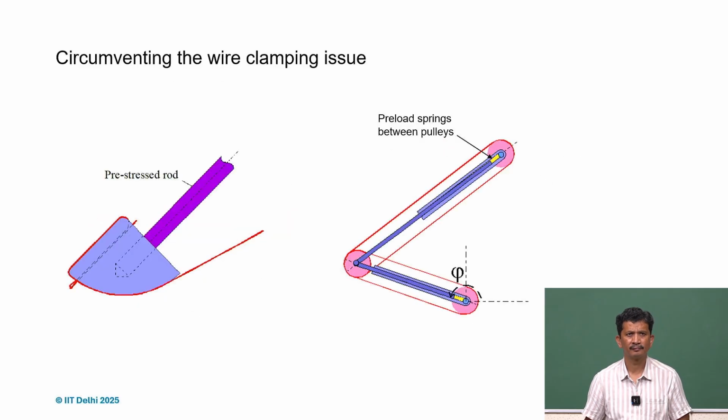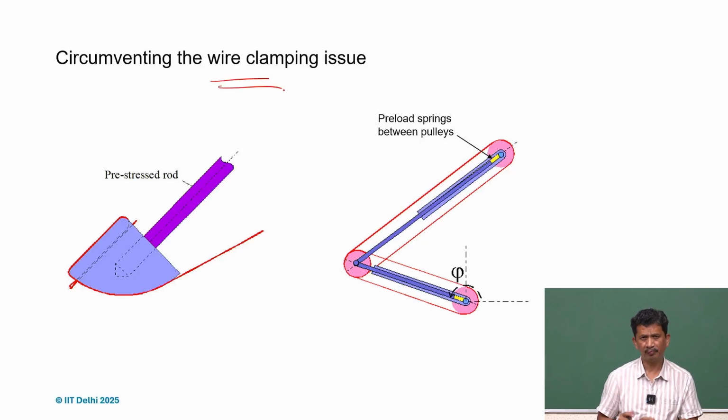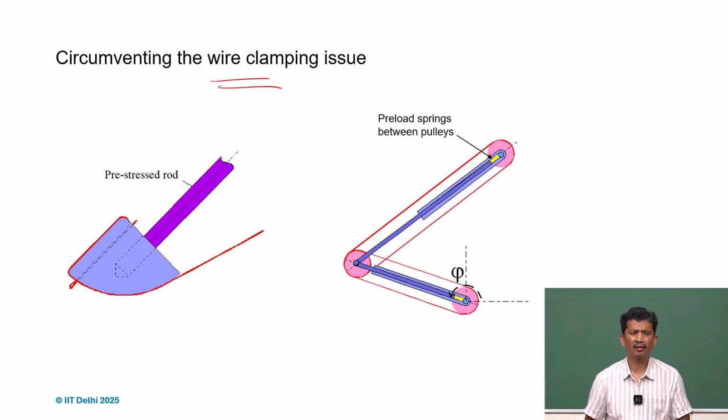So what we also realize is that a simple flexible wire can also provide us the required constraint in one direction. If it's intentional, and if we can ensure that the loading in the wire is always in tension, it can also give us a very good constraint device or constraint mechanism, or compliant mechanism, what we can say.